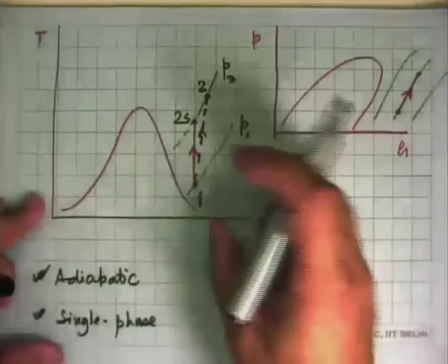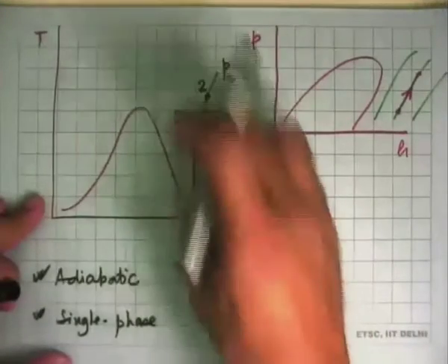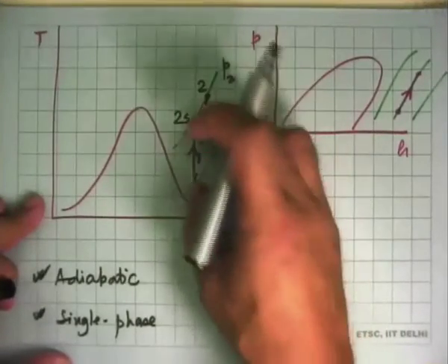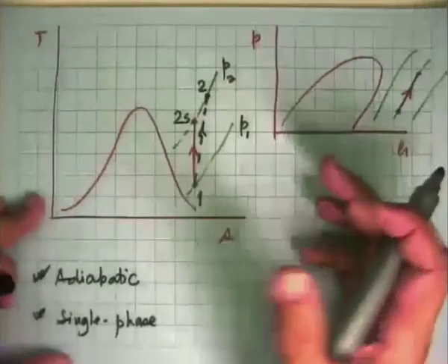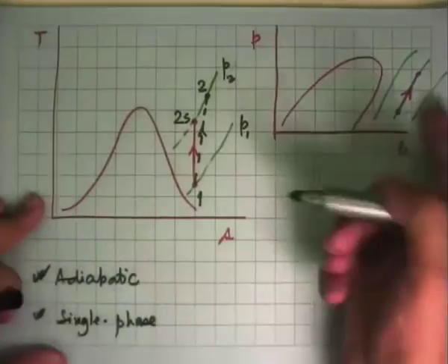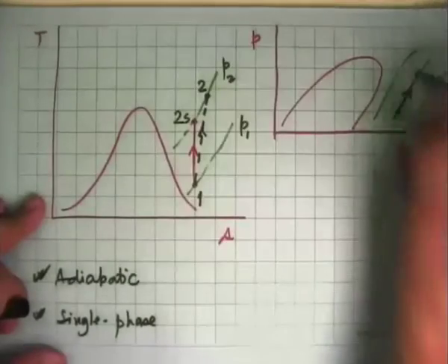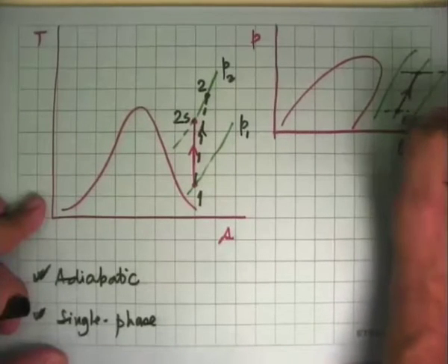So if you have to calculate the real work from the isentropic efficiency, or if you have to calculate isentropic efficiency, we need to know one of these things. Either this change, the P change, or the work input. And two of these are known, the third one can be calculated. On the PH diagram, the discharge pressure is going to be the same, inlet pressure is the same, but entropy has to increase. So these are the lines of increasing entropy.